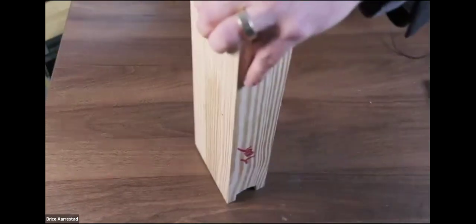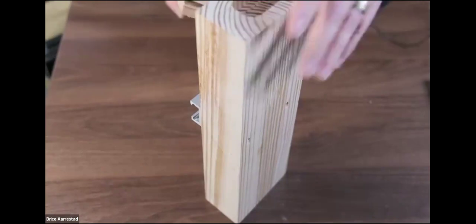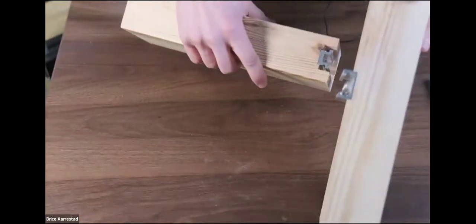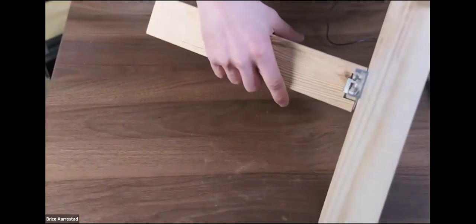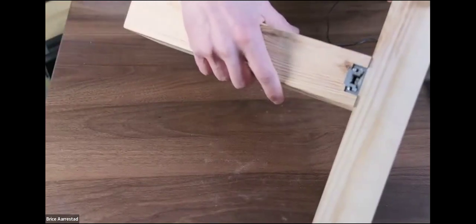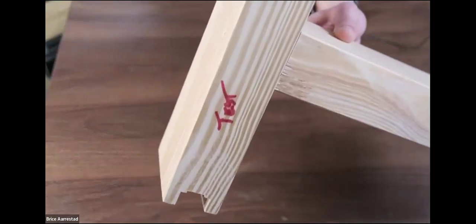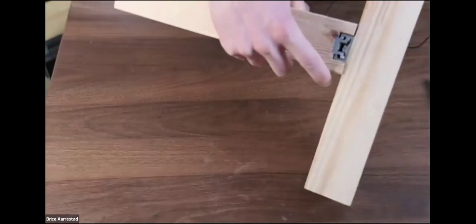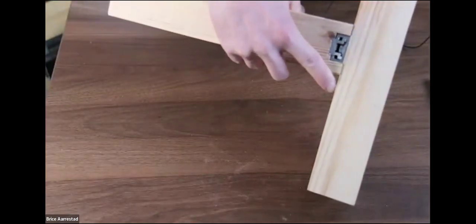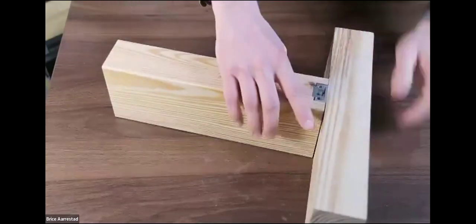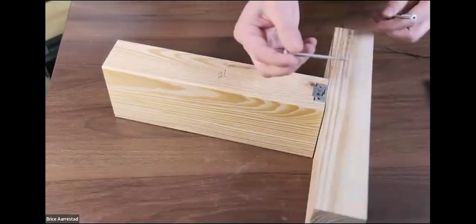And this is usually done from the back. So if I turn it around here, if you're looking at it from the face of the curtain wall, it slides in from the back to the front. So this would be the back side there. It's a hidden connection on the back. On the front side, it's going to get glazed over anyway, so you won't see it. And then the way it's secured is using 2 nail screws.